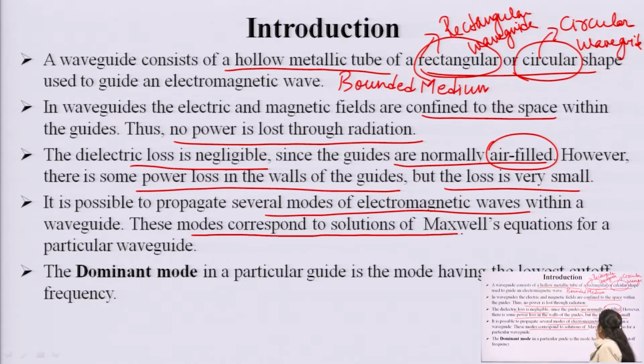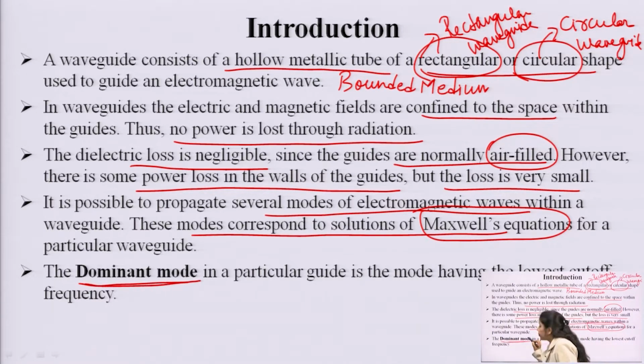These modes correspond to the solution of the Maxwell equations and we will go in depth in this section. Which frequency and which wavelengths can pass through a particular waveguide depends upon the dominant mode. Dominant mode is basically the particular mode of the guide having the lowest cutoff frequency.